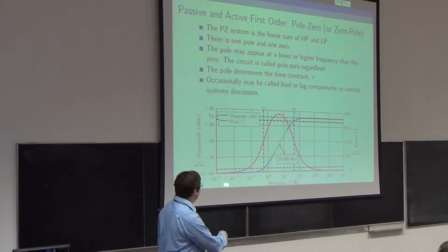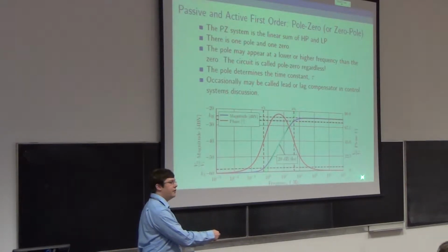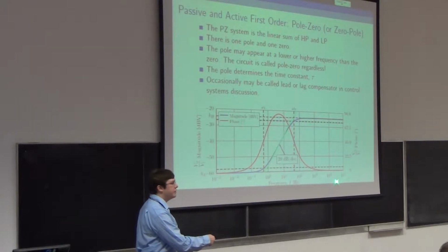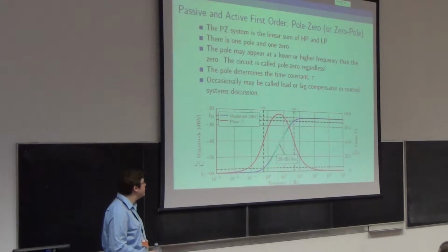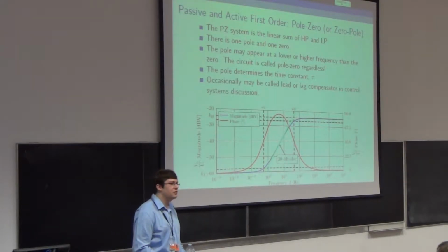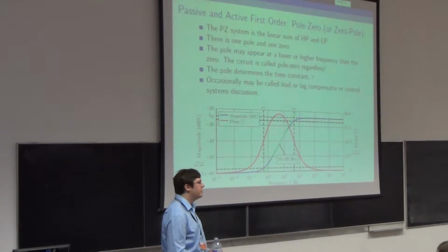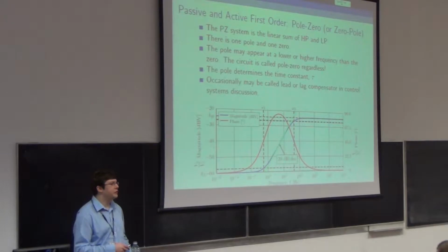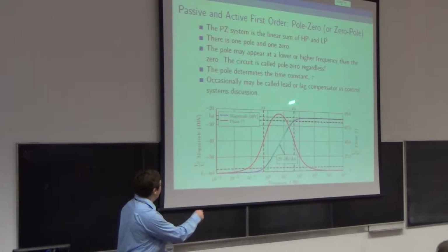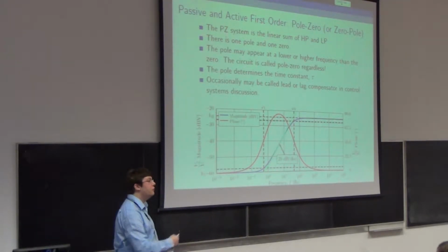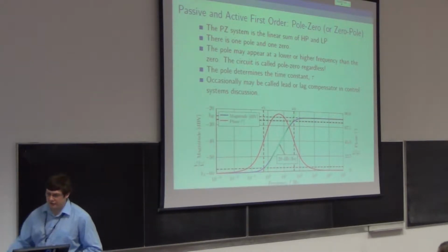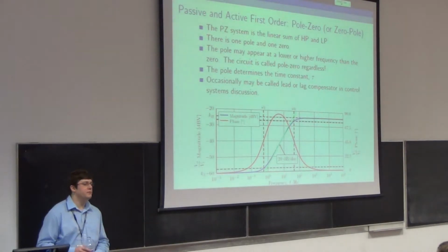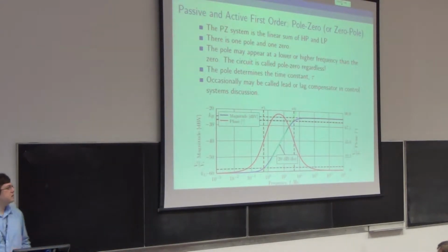Because if you look at the number of orders of magnitude I've got on F here, even to get most of the way to 90, I've gone from a millihertz to 100k. There are only a few times when you want a circuit with such an enormous bandwidth, and you won't have to start worrying about microwave effects. So it's actually quite unusual to find that all the way up and then down again. Although there are some times, especially in the feedback of analog amplifiers, where you do end up with enormous bandwidths involved. But usually you'll see in a textbook drawn like that.